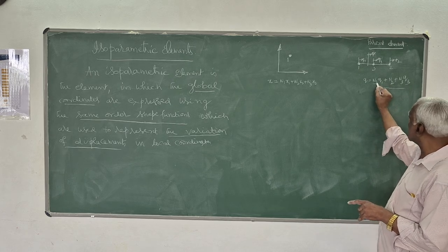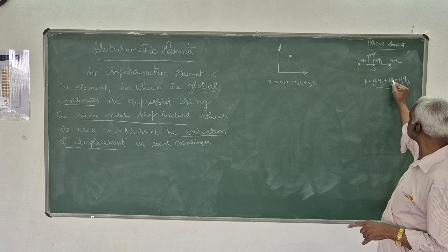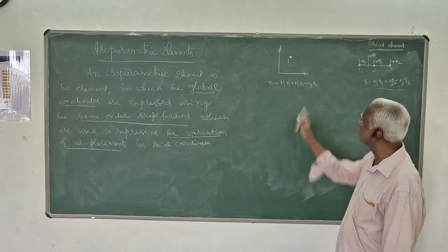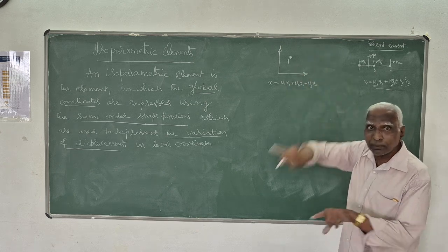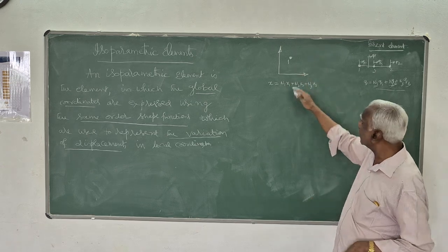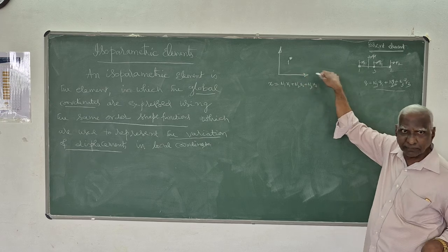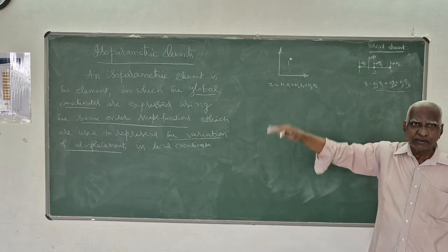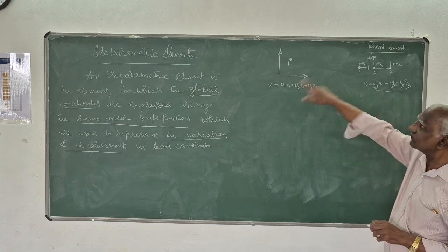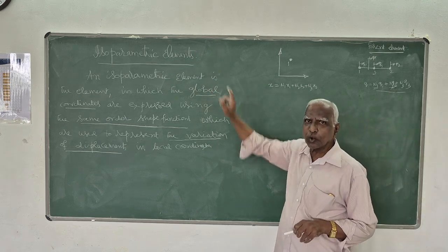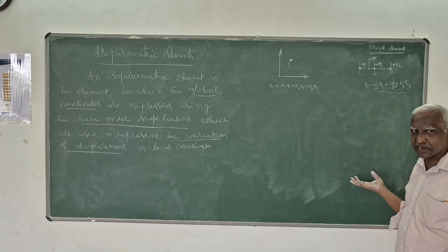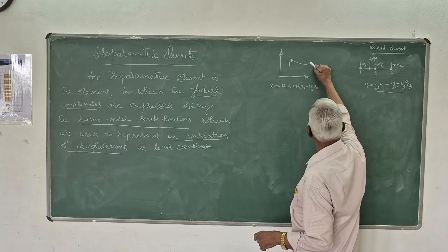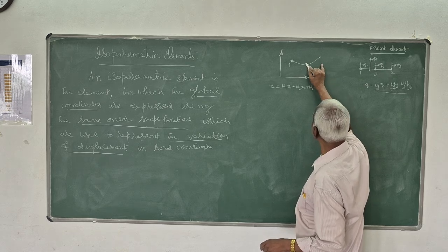Here, if you use the same shape function, whatever you have used to represent the displacement, for representing the coordinates, then the resulting element of the transformation, whatever the element shape you are going to get, that we call the isoparametric element. That's what we call it. So this element may be of some shape like that.